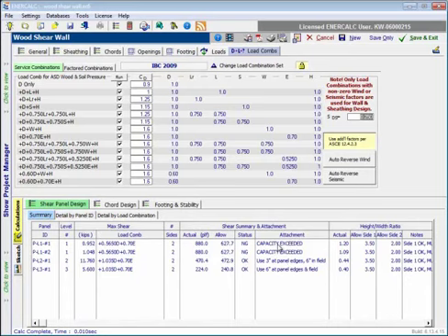So if we had played around with some stronger sheathing, or if I had assigned slightly lower loads so that we had everything working okay, we would be able to see that we would have fastener patterns indicated for us. And remember that way back at the point where we specified sheathing, we've also specified the fastener and the minimum fastener penetration. So all the information is now provided for us. We know what fastener, and here we know what spacing to use.